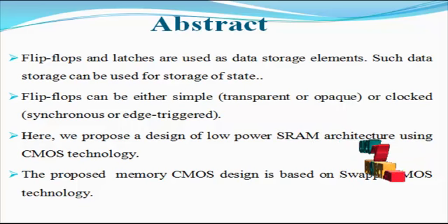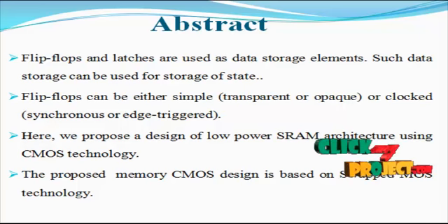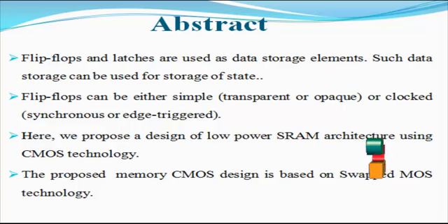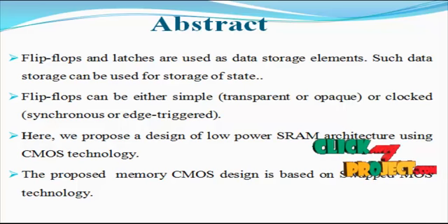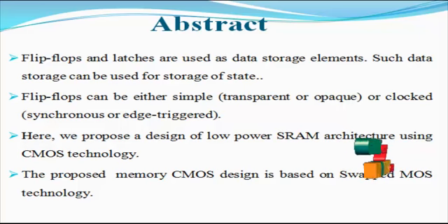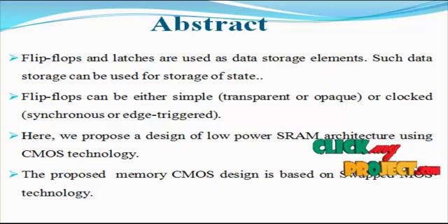In this paper, a new approach towards the design of a memristor based non-volatile static random access memory cell using a combination of memristor and metal oxide semiconductor devices is proposed. Memristor and MOSFETs of the Taiwan Semiconductor Manufacturing Company based on 180 nanometer technology are used in the form of a single cell.